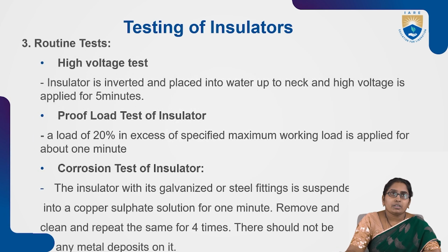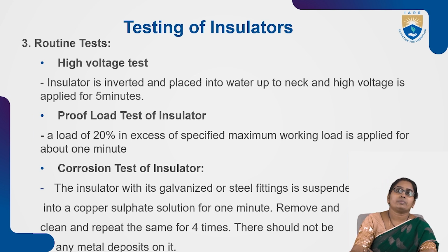Next, the third type of test, routine tests. Under this there are three tests. First one, high voltage test. The insulator is inverted and placed into water up to the neck, and a high voltage is applied for 5 minutes.